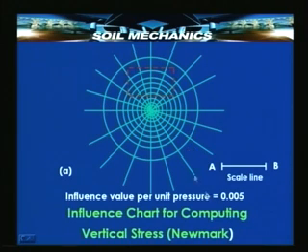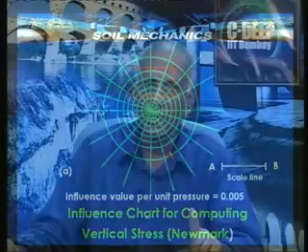This chart gives you, for a predefined depth scale, different R values and corresponding areas with the same influence factor. This means that every single sectoral area that we see here has the same influence coefficient value, because for each one of them R upon Z remains the same.